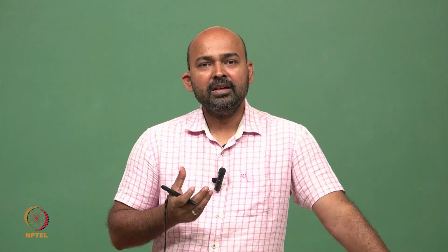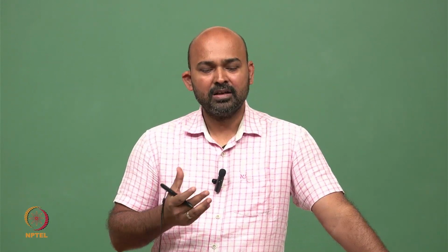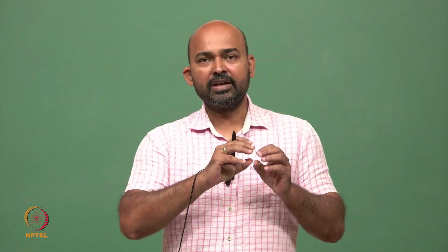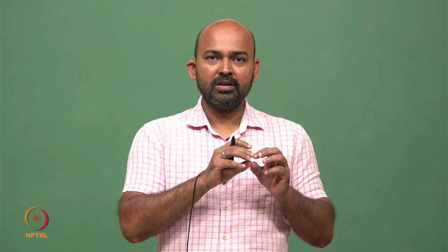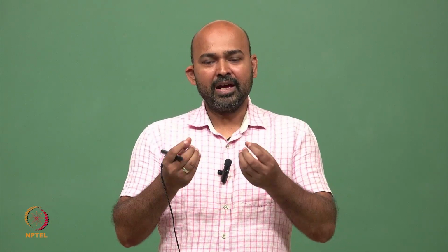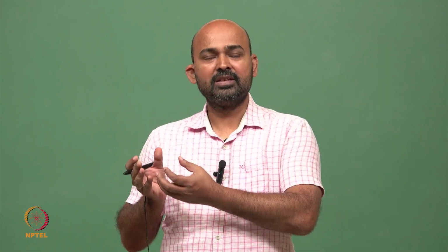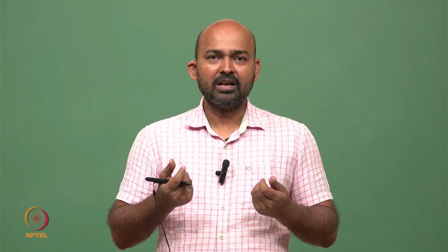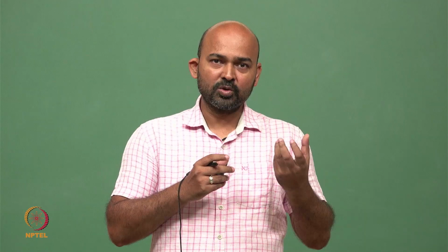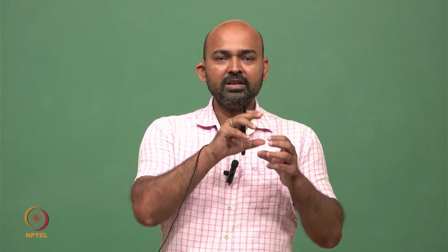This RFID system primarily has three parts. The first one is the RFID tag, where the data is stored, the identification key is stored. Then we have some sort of antenna in this RFID tag as well as in the receiver. These antennas use RF waves for communication. So whatever data is stored in the RFID tag is transmitted using these antennas.